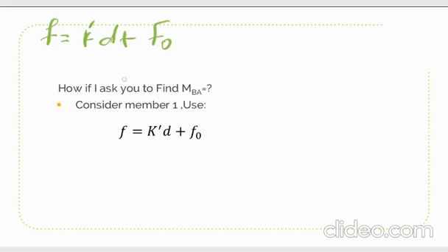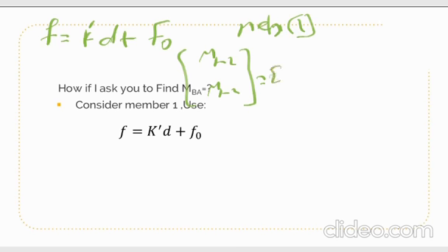F, as I said, is M12 and M21, the moments. Here we talk about member number 1. We take K11, and I take EI as a constant, and the value of K is 0.44, 0.22, 0.22 and 0.44.